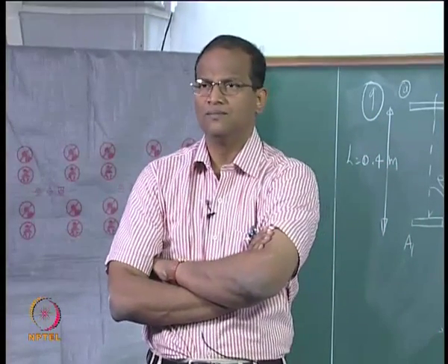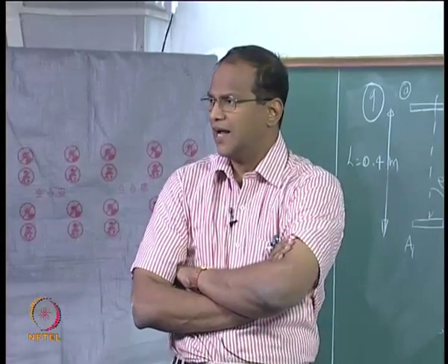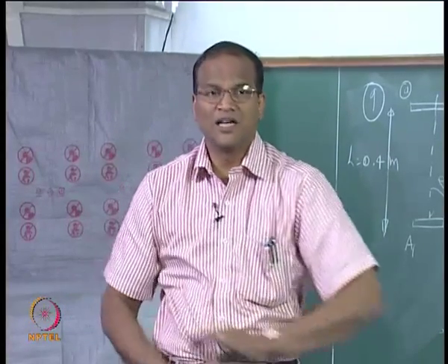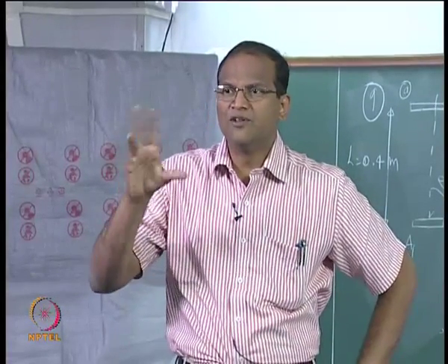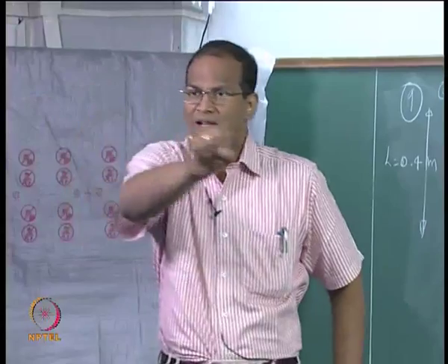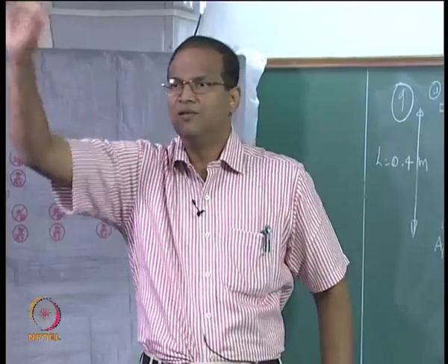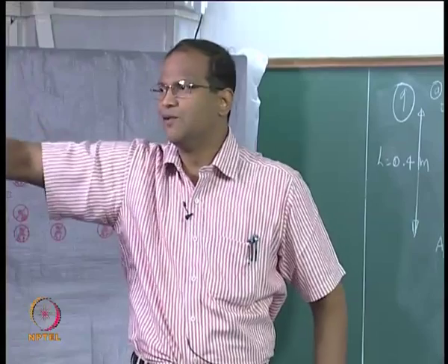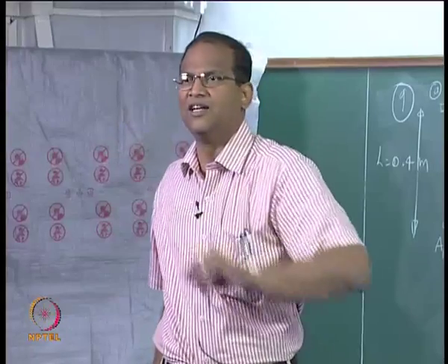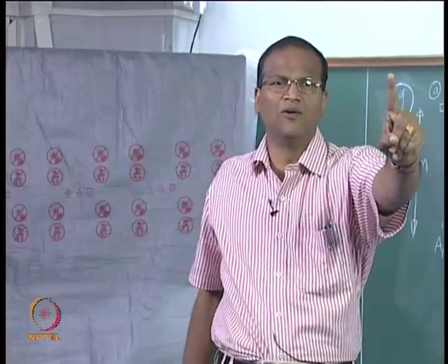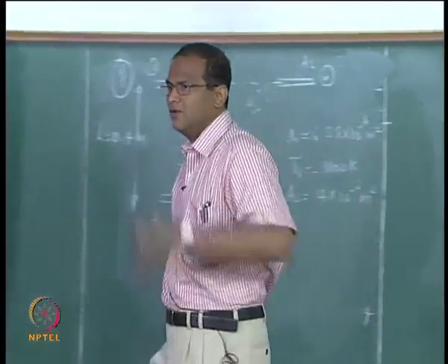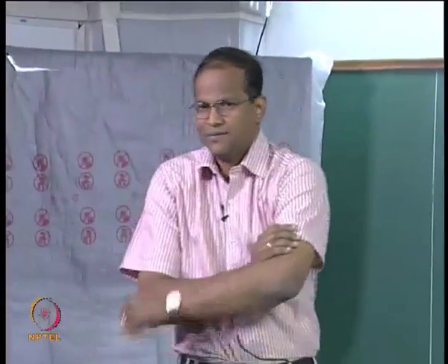You must use Stefan's law, you must use the concept of solid angle. Originally when I started out with solid angle, I gave you the emissive power. Now we have gone through 10 or 12 hours of this course, I will give you the temperature and you have to multiply it by the emissivity. Now using solid angle, on the right hand side you will get an expression where only one unknown will be there, that is epsilon dash of theta. Left hand side you know what power the detector is measuring. Solve for only one unknown, that is epsilon dash theta at theta equal to 0. Please do the first part, the second part will automatically flow, but the radius will change now.